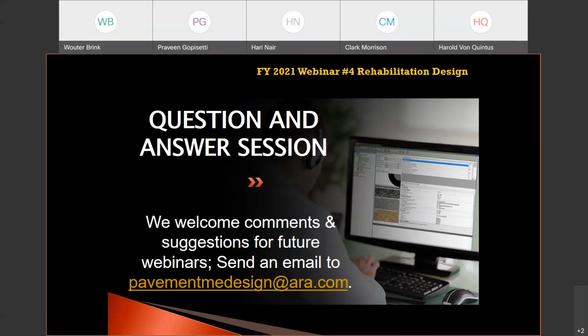Okay, thanks, Harold. The next one here is from Paul McKika. Would fractured JPCP be an appropriate choice to model a severely deteriorated underlying concrete pavement? An example, a concrete pavement that was not specifically rubblized or crack and seated, but has a low FWD modulus and cores show significant cracking. Yes, you can.